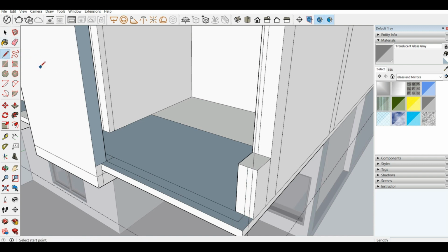So here the basic height which we thought of for the railing is 3 feet, but the height of the glass must be less than that, so that the railing bar can also be built above the glass. So for now I am just keeping it 2 feet 10 inches. That is done. I'm joining it here now.